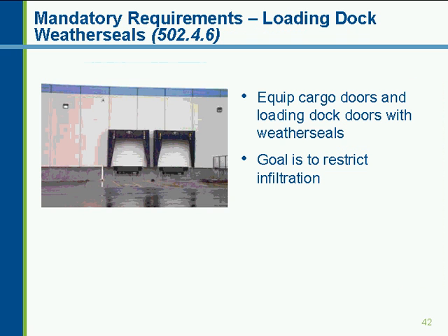Other ways of reducing infiltration air for conditioned loading docks: the code requires loading docks with Weatherseals. So when you back the tractor up into the loading dock, it actually seals around the back of the tractor and reduces the infiltration load going into that loading dock. And this will reduce the energy needed to keep that loading dock at the temperature. There are no set requirements for loading dock Weatherseals. There's no ASTM testing and that type of thing. It's in the code. It basically just says use a Weatherseal or a loading dock Weatherseal on this one, but you're trying to reduce infiltration for this particular building.